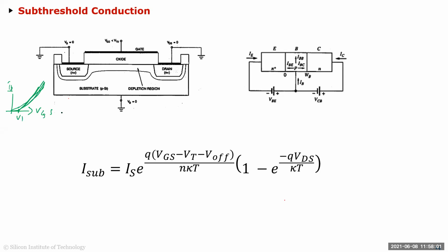And that's what's called the weak inversion region of operation, which has conduction. When you get to VGS equals VT, the channel is obviously formed, but before that it's not magically off. That's just an arbitrary point we took to make our life easier. Before VT there is also a channel, but it is weaker, and then a few tens of kT, like 26 millivolts or 100 millivolts before VT, there is no channel, but you can still have conduction with diffusion, just like in a BJT.